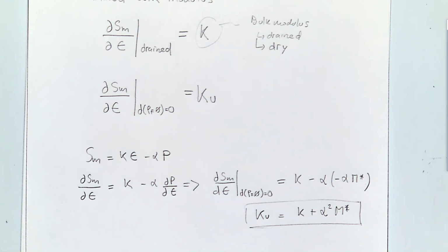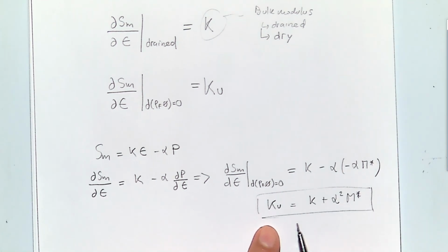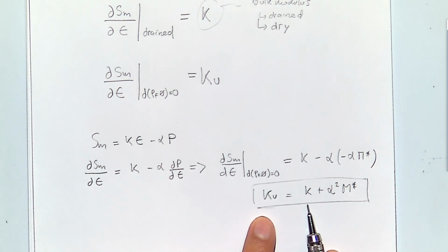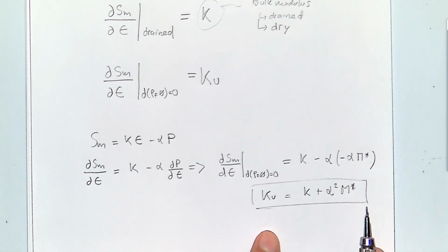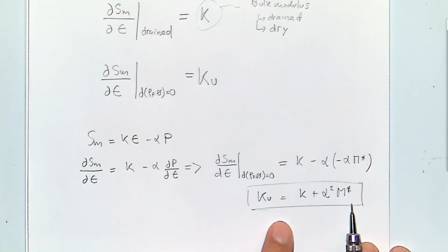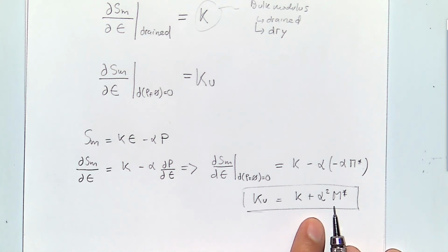You run it in one day, in a few days at most. And in many of those cases, I think what people really measure is the undrained modulus, not the actual drained modulus. And you have to be careful about that, because these are not the same thing. Sometimes if the rock is too tight, you might be compressing the fluid inside without knowing that.